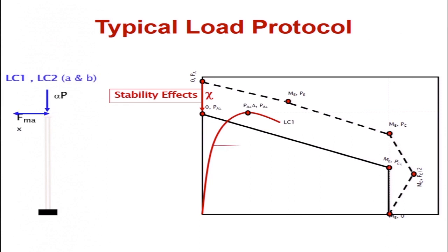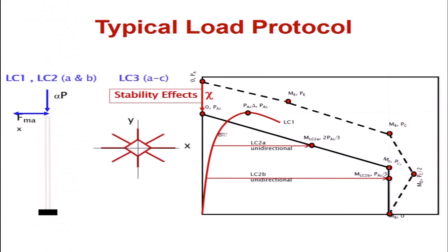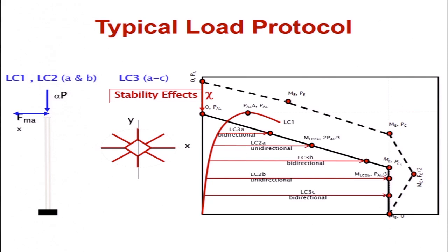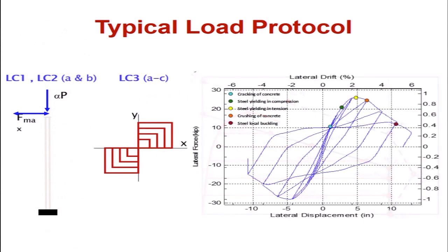We then did a number of combinations of axial load and unidirectional lateral loads to look at different points along the interaction diagram. We did that initially in one direction, and then we did bidirectional, right? And because we had the best toy in the industry, we went ahead and did crazy things like this, which actually are very good tests of whether your analysis can track things. This is a very complicated load history and sudden changes in direction and so on.